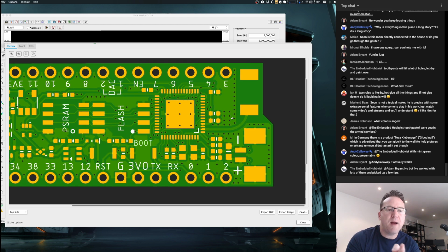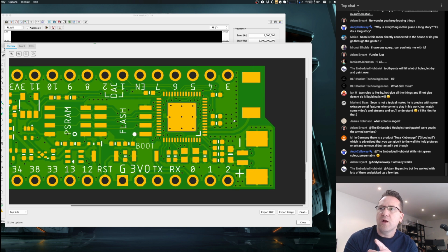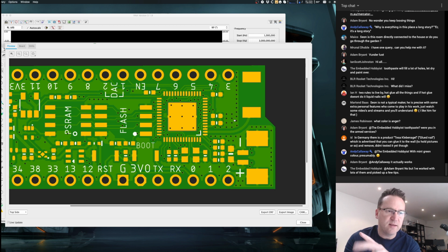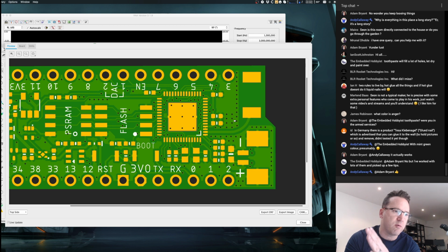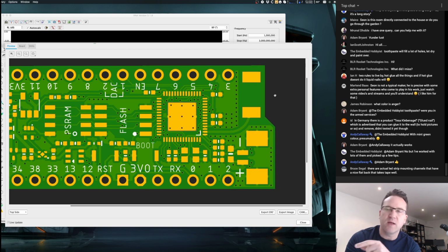And so I want to see how much difference there is between having a matching network and having no matching network. To use the board that's got matching network pads on it, but not put the matching network on, just putting a 0R resistor, isn't the same as what we see here, because there's still a whole lot of pads and traces and extra length, and so that's going to affect the impedance on the trace. So it wouldn't ever really tell me if it needs a matching network or not. The only way to really know is to do something like this.